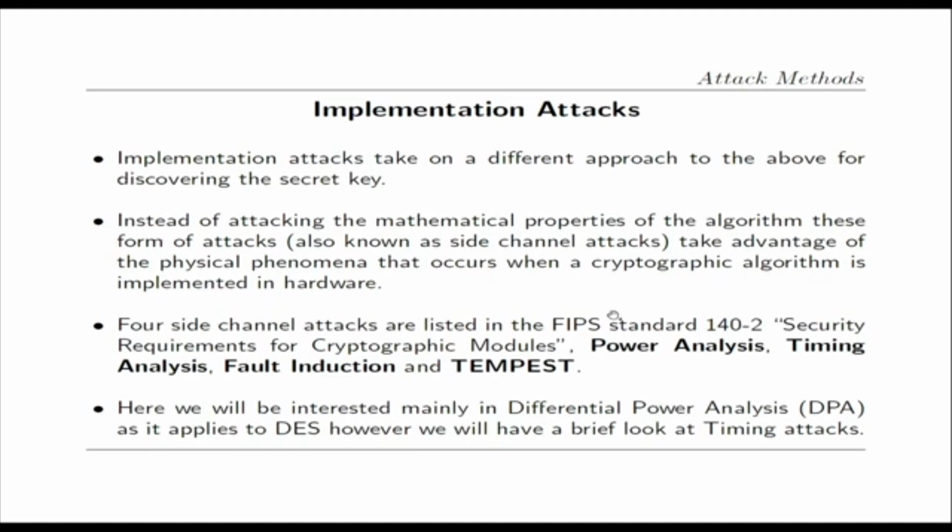There are four types of side channel attack listed in the FIPS standard: power analysis, timing analysis, fault induction, and TEMPEST. We will talk mostly about power analysis, differential power analysis (DPA), which is applied to break DES, and then we talk about timing attack also in this lecture. So let us talk about